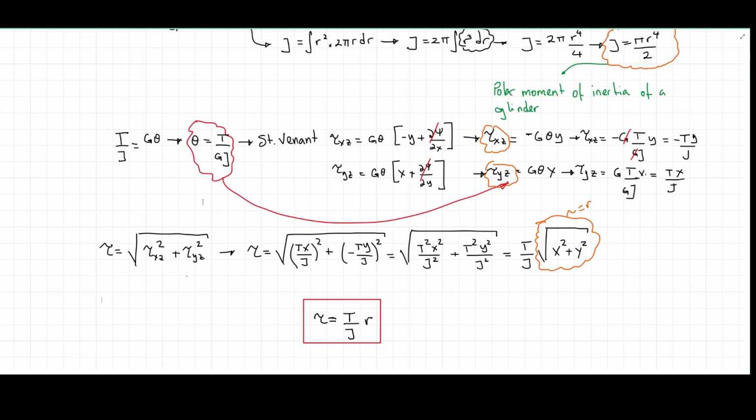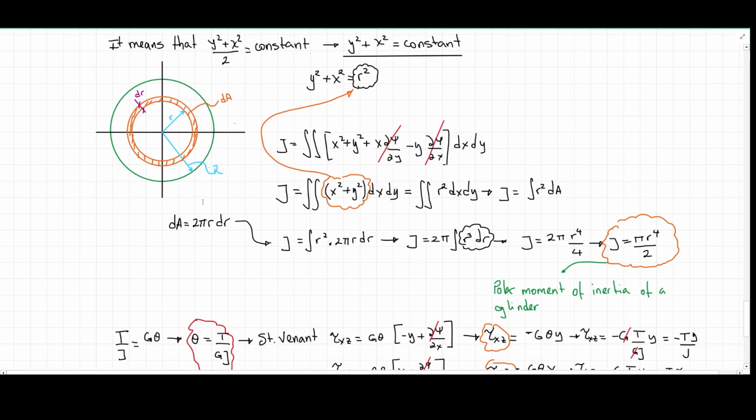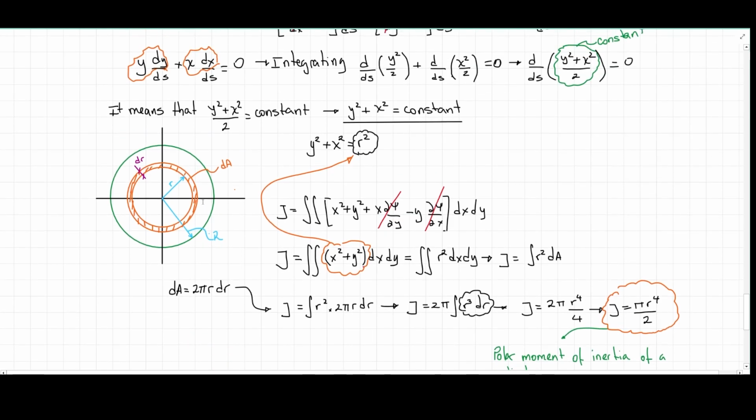If the section is circular, it's a piece of cake because you don't have to take warping into account. But if you have a non-symmetrical section, you have to work a little harder to get the equations that define the boundary of the surface so you can calculate the torsional constant and then find out those stresses.